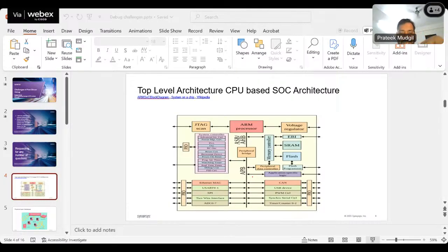But that is definitely a challenge for us. If you see, this is again copied from a Google search. It is talking about picoseconds, right? So you can see how small the eye is. You can say 80 to 180, around 100 picoseconds, right? So the eye is very small. So it is very difficult for us working at Gen 6 and Gen 7 levels to transfer the data, right? And even at that level, when we are transferring the data and the eye is very small, we are facing some silicon issues. It is a very big issue for us to debug, right? And this is an analog block, right?